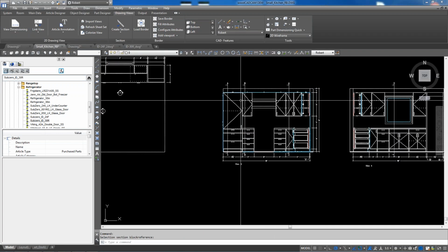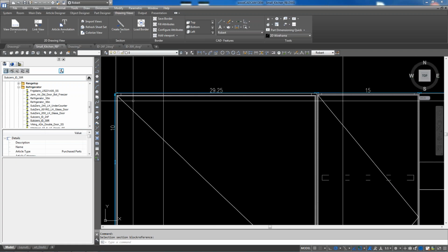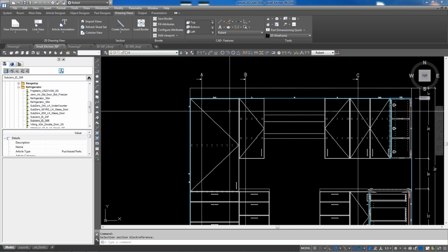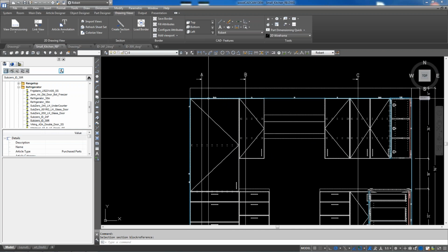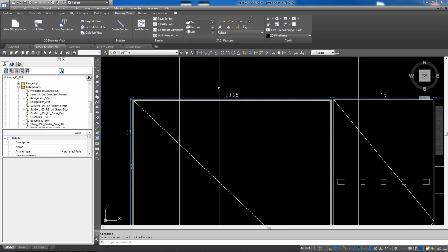Okay, zoom out so you can see it. Oh, interesting. So they're doing some kind of weird scaling, and I haven't got a good explanation from the Germans of what they're doing. Based on how much you're zoomed in and out, basically the scale that you're at, they're adjusting the dimensions based on that. So what I like to do is uncheck that box so I can control it myself. Then it doesn't do that scaling for me. So go ahead and delete the annotation there.